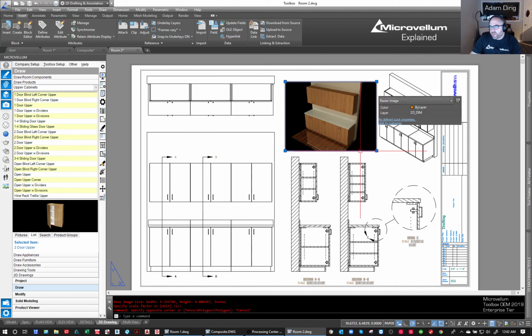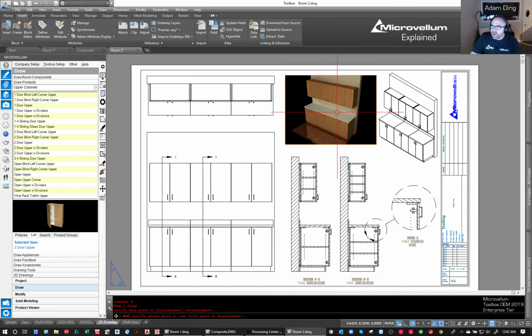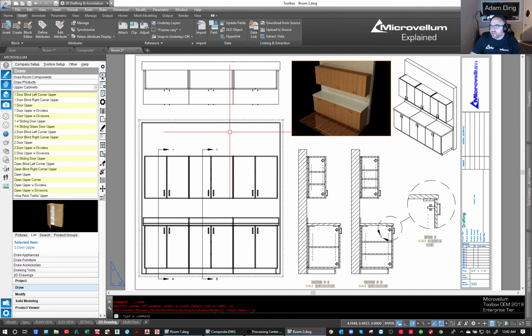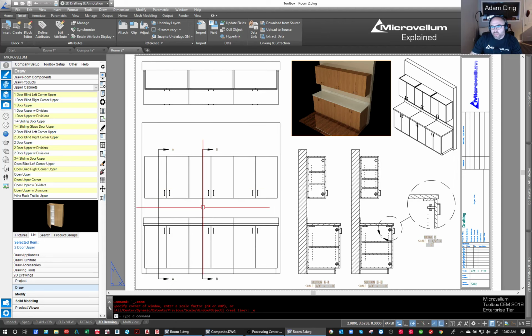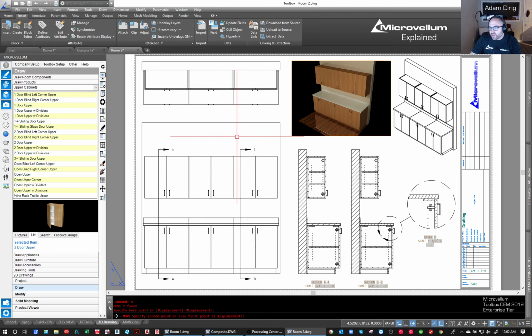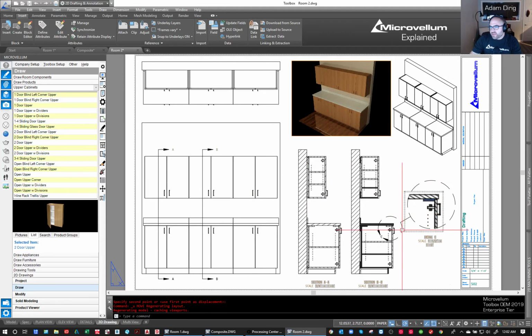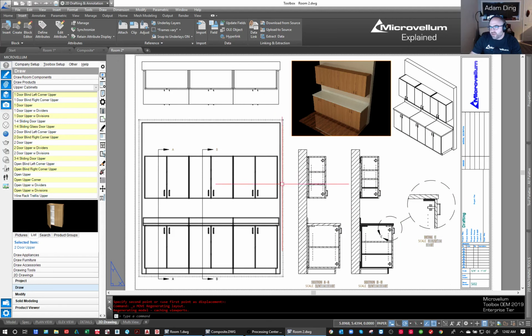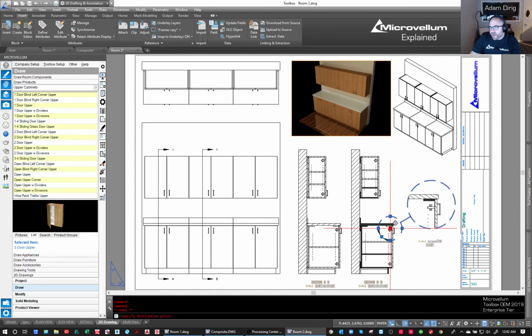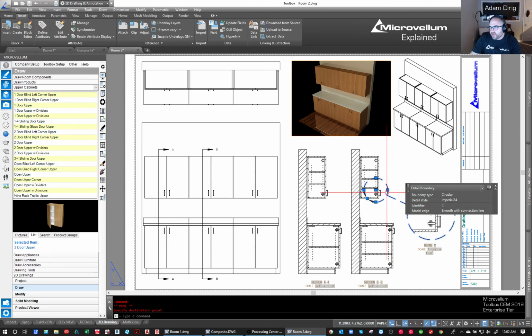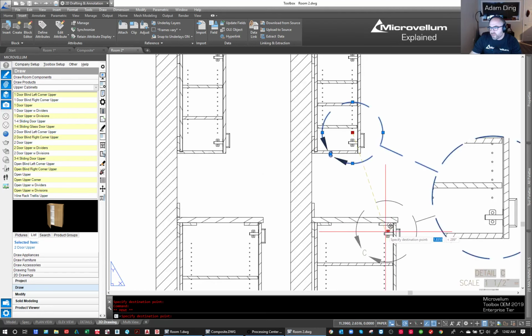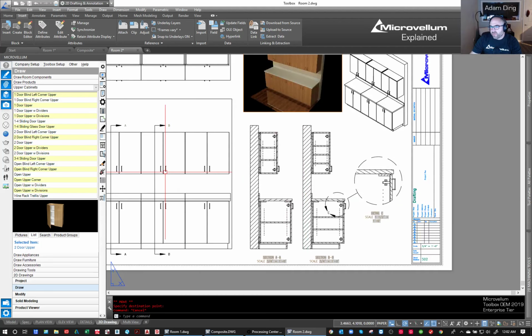So this is a great way to do a presentation drawing for an architect or an engineer. You could even do shop drawings this way too. You could see it did not take me that long to do. What's cool about these sections too is they're completely dynamic. You move them, they update. Same with the details. If you move this detail to another spot, it updates. Very cool feature of AutoCAD.